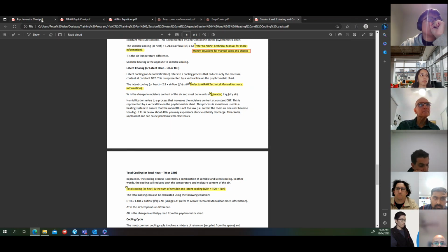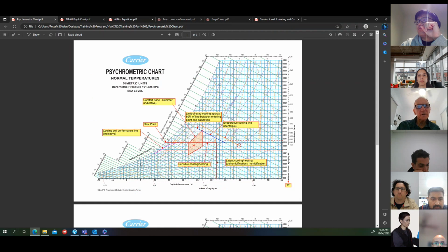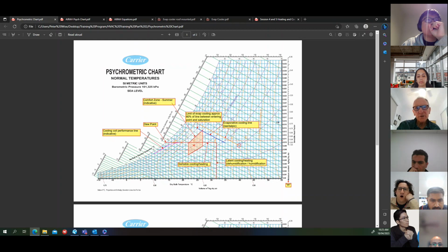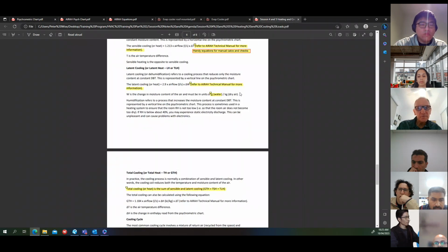So when you look at the psychrometric chart, again, these are just stylized processes, but if the air is cold, let's say it's 5 degrees and you're heating. So you start over here and you're heating along the constant wet bulb line. You can see that the humidity is getting quite low. If it starts at 5 and you get to 20 degrees, the relative humidity is already down to about 35%. Don't take that as gospel, but this is just an example. That's getting a bit too dry because 40% is probably as low as you want to go with humidity.